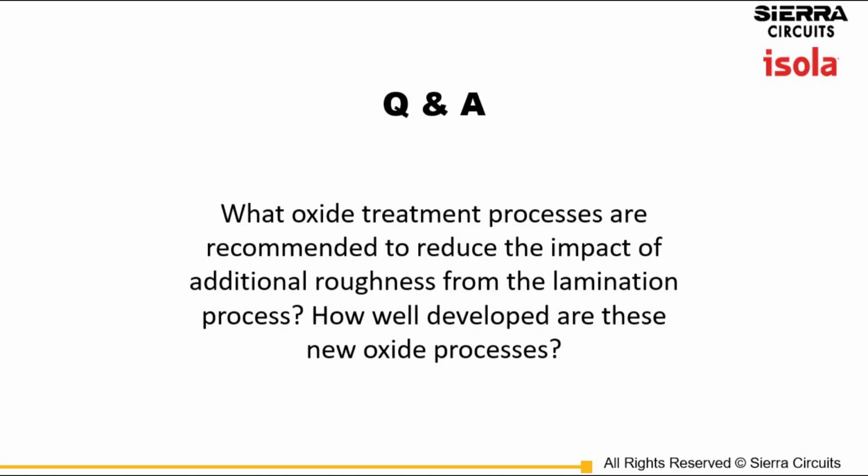Okay, are we ready? Who is going to take question 1 from Brad? What oxide treatment processes are recommended to reduce impact of additional roughness from the lamination process? How well developed are these new oxide processes?